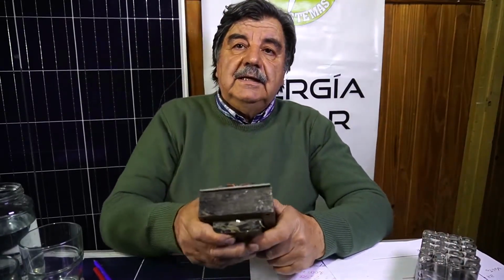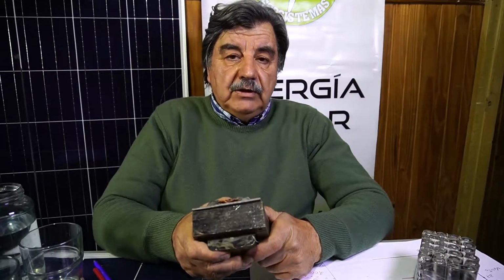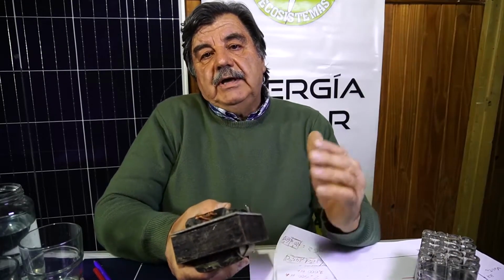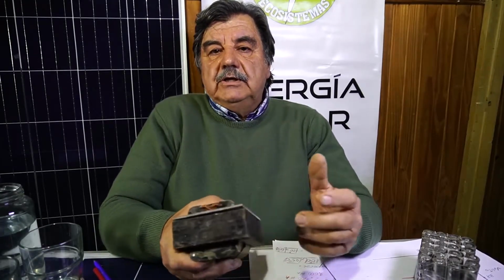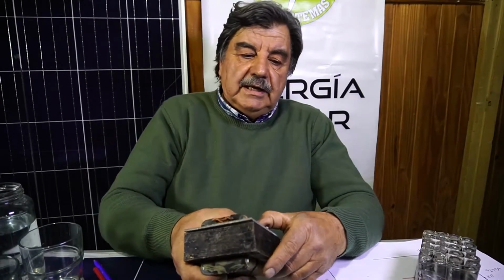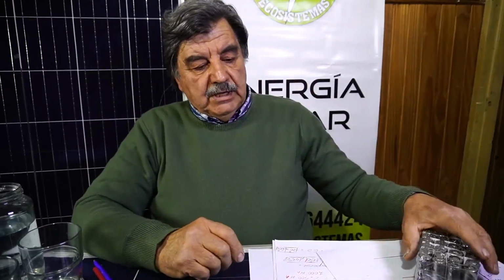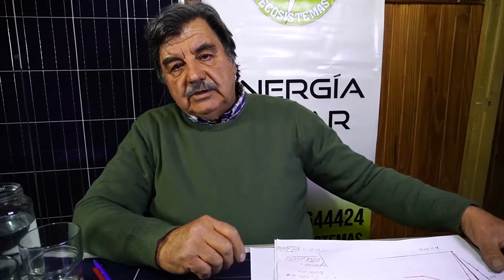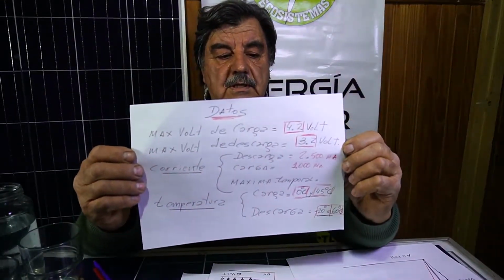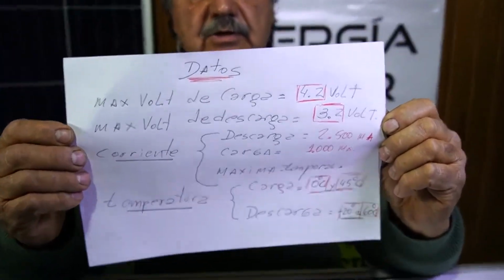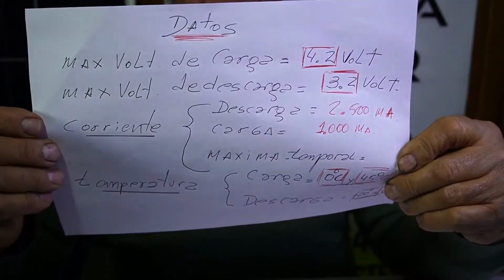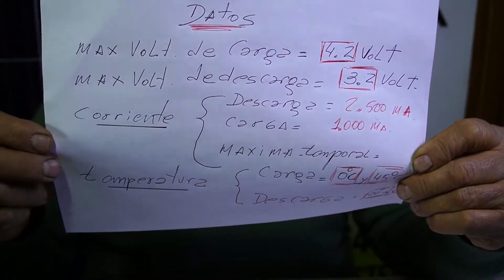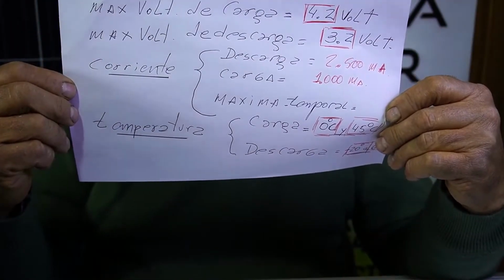What must be taken into account is that the purchased chargers, the serial chargers, have built-in controls. Because if I put a higher source and I don't control the charge, yes, it can damage the battery. So, what can I do? Look for the data sheet that the battery has. For example, this will be the data sheet for a lithium-ion cell. This data sheet has the most important data. I transposed them onto this paper so I could explain it to you.